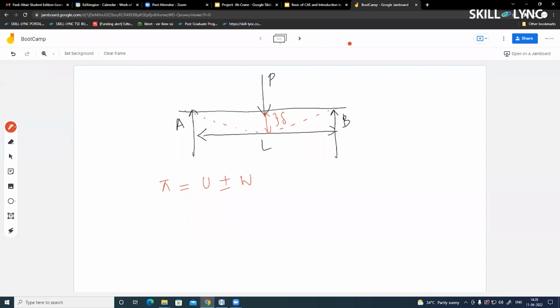In any case where we apply loads, you might have gone through the stress strain graph for various materials, so you might have an understanding that if any component is under loading, and we remove the external load before the elastic limit, the material will regain its original shape. This property of the metal is what we call elasticity. And if you see carefully how this material comes back to its original shape, you'll understand that this is because of the strain energy stored in the component.